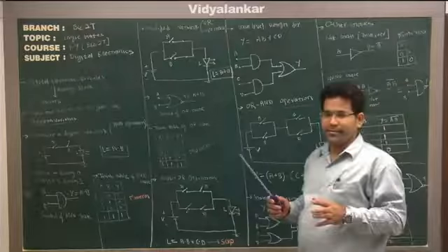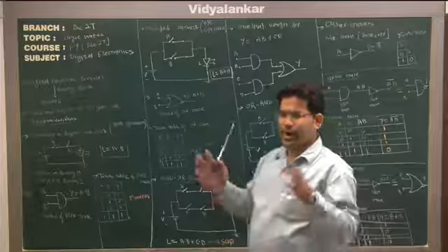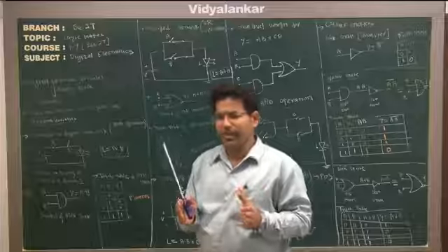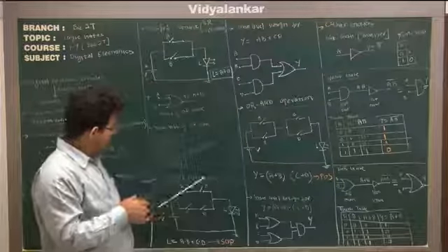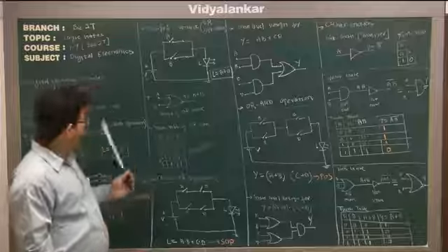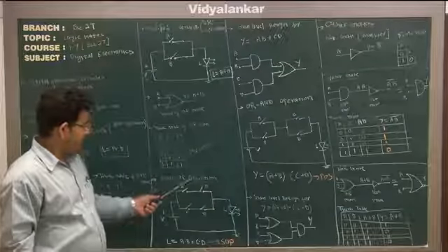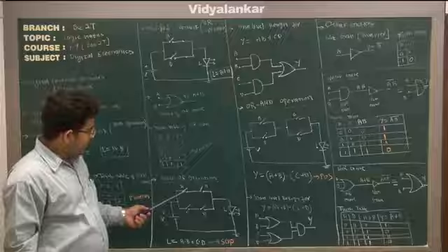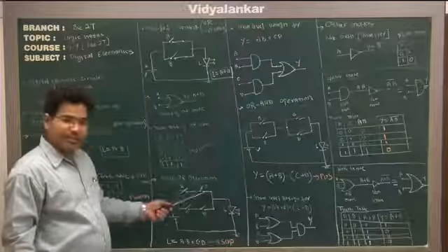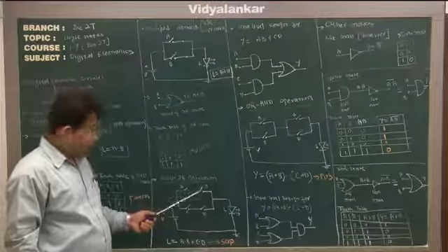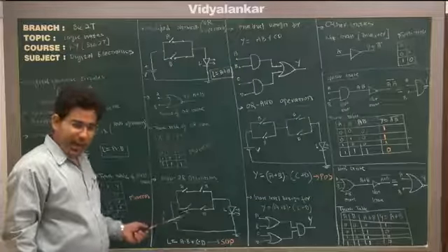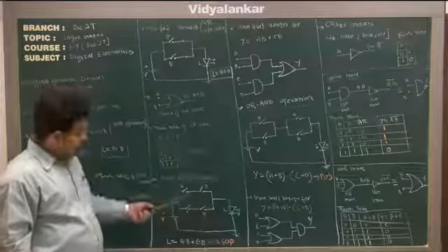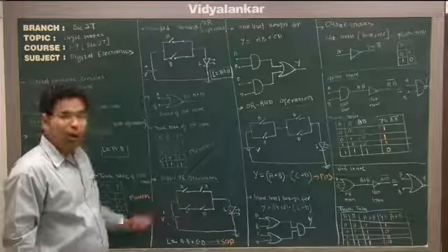If I combine this in digital electronics, we need a larger circuit. This is a very basic building block, so the actual circuit will be quite large. So just one example where we combine both of these operations, AND and OR. So what I have done is A and B are in series, means AND operation. C and D are in series, again AND operation. Both of them are in parallel, means OR operation.